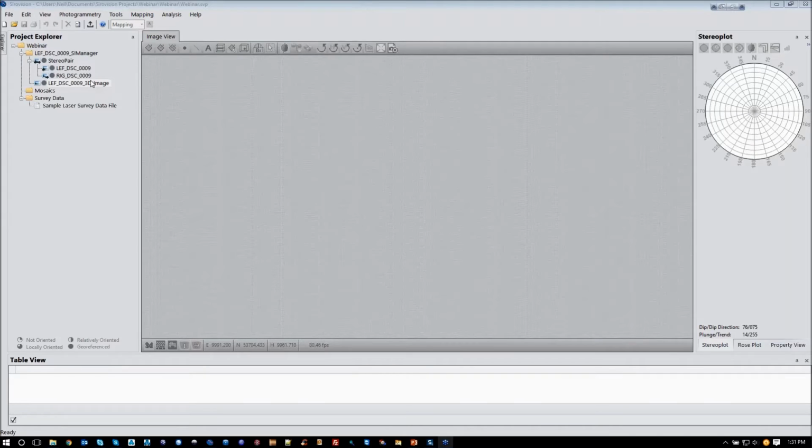Okay. And is the crosshair method more accurate than the traditional method of georeferencing? I don't think there's a difference in accuracy. I think it's more just accessibility. A lot of the time, surveyors in an underground scenario are very busy. They have a lot to do. And if you don't want to have to rely on them, you can use this methodology so you don't necessarily need to rely on a survey team to pick up the points on the face, especially if your mine site workflow involves a lot of shotcrete, because you could lose those points before you get a chance to georeference your image properly.